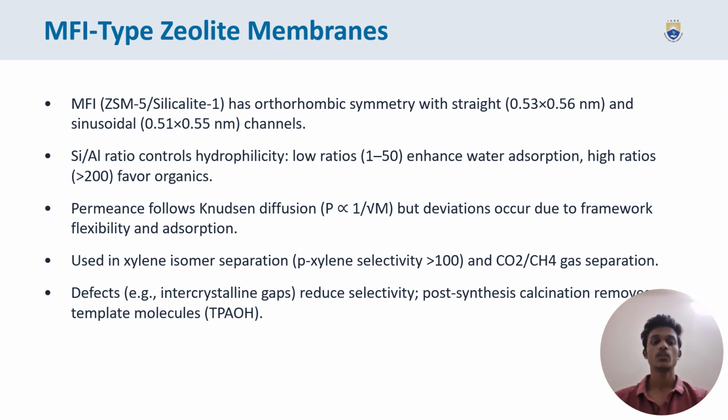MFI type zeolite membranes. MFI has orthorhombic symmetry with straight and sinusoidal channels. Silicon to aluminum ratio controls hydrophilicity. Low ratios, 1 to 50, enhance water adsorption. High ratios greater than 200 favor organics.